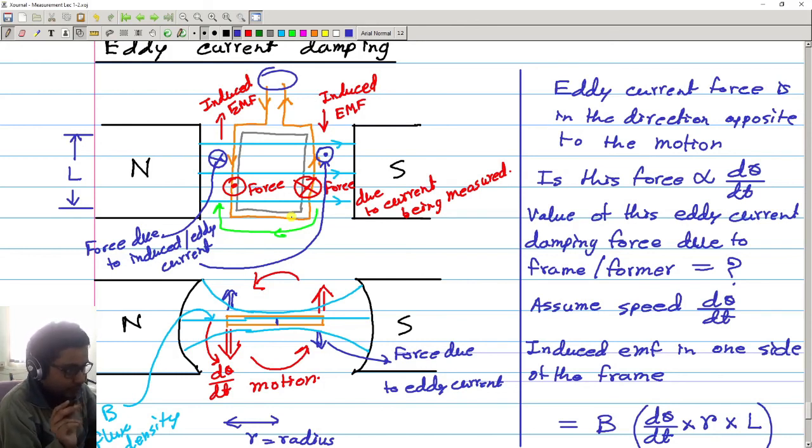So we don't need to do any calibration, because we will take the reading after the pointer settles down, and at that moment there is no eddy current, because the pointer is not moving, the coil is not moving, so there is no induced EMF, no eddy current. So no correction at all is required. That is the beauty of this thing. Yes, sir, got it.